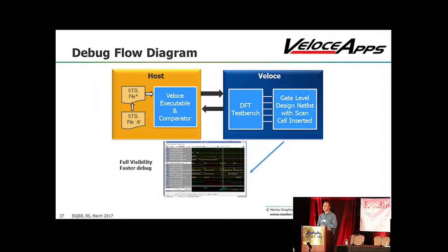You can generate these waveforms real time. As the emulation is running, the waveform database is being generated. You can pull it up in your waveform viewer, in this case it's Visualizer, and debug it on the fly.